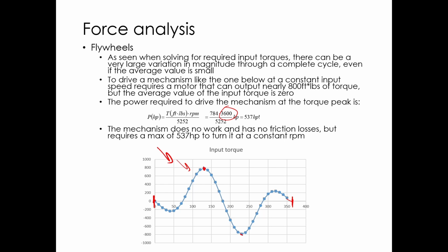And this is all happening in a cycle. So at 3,600 RPM, that's 60 hertz, so 60 times a second. So this curve is happening in a 60th of a second. So you get really big vibrations. So this would be a 60 hertz vibration. This has got some second order harmonics in it. We'll talk about that later on. But the main trend here is basically at the frequency that it's running at.